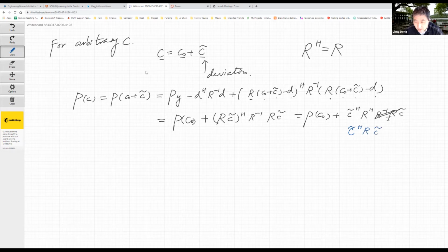All right, and this part in blue, we call that the excess mean square error. That's the error beyond the minimum mean square error, something caused by the deviation of the parameters you choose. So I have some non-zero error, which is beyond the minimum mean square error, beyond this error here. Okay. So with the concept of an excess mean square error,